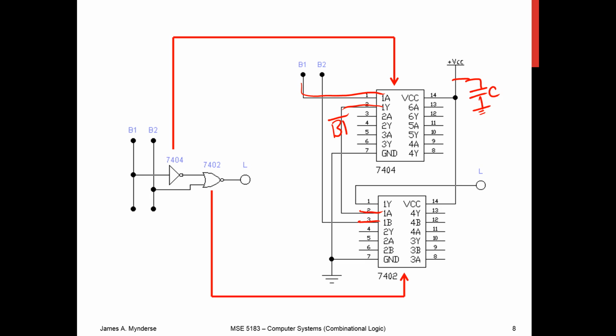So this is just a capacitor between the power supply and ground, and I put it as close to the chip as possible. And, for that matter, I probably want to put one on each of them. When the chip is active, it may occasionally need a little more current, and so the bypass capacitor is storing energy. When the chip needs a little more current, kind of like a fan on your external AC unit that needs a little kickstart, it'll draw it from the capacitor. So it's a quick way to get current, and it helps supply the power to the chip.